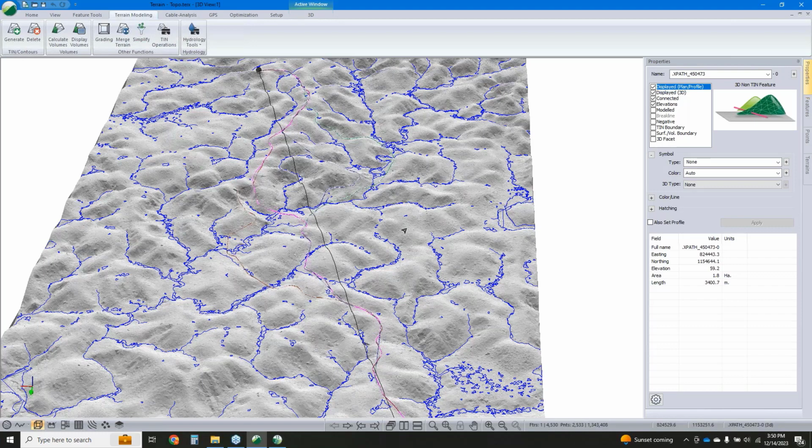Unrelated to the question, one thing that I'm kind of surprised by running it myself: when designing switchbacks myself, I'm usually putting in something that's tight, close to the limits, and letting the optimizer run through it. It often lands on broader switchbacks, which are nice from a constructability standpoint, nice from a driver standpoint, and it's also reducing costs. So just an observation from someone that's played around with it as a designer too. It's pretty slick.